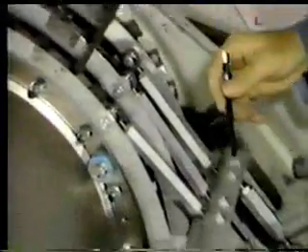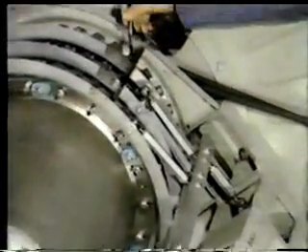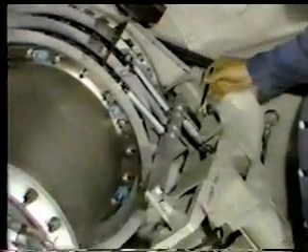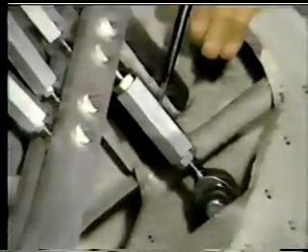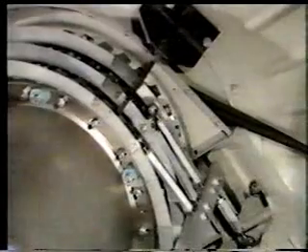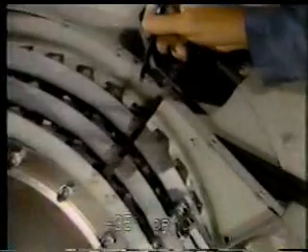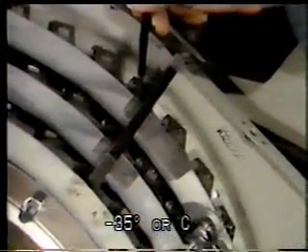The reading on the scale of the inlet guide vane should correspond with the stencil setting on the housing. If the scale does not match the indicated reading, the lever arm turnbuckle must be adjusted. Adjust the turnbuckle so that the scale reading matches the stenciled reading. Shut off the oil pressure and reverse the oil lines. Pressurize the actuator and retract the vanes. The inlet scale should read -35 degrees or C.